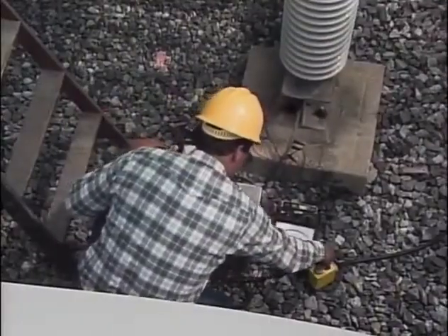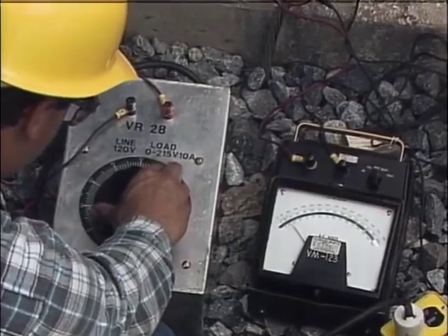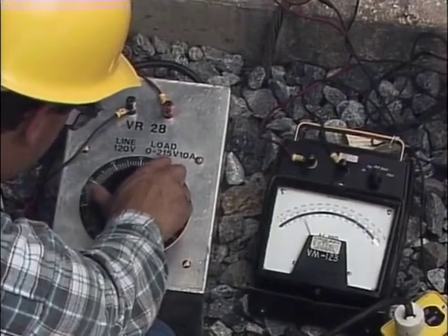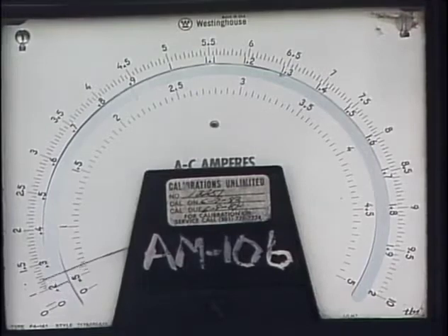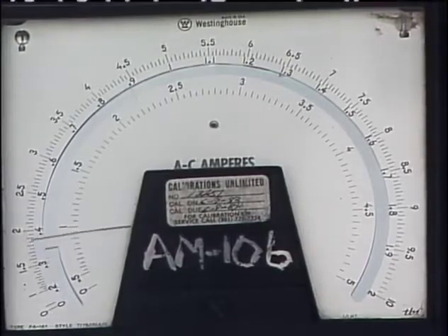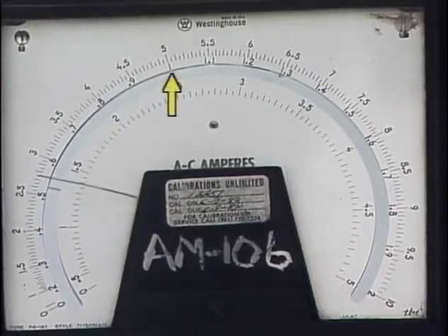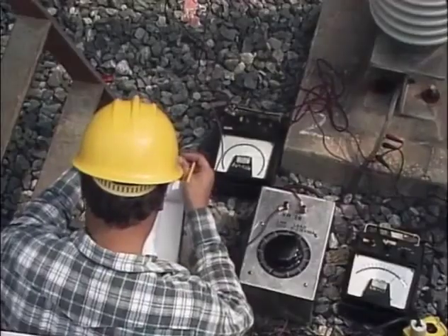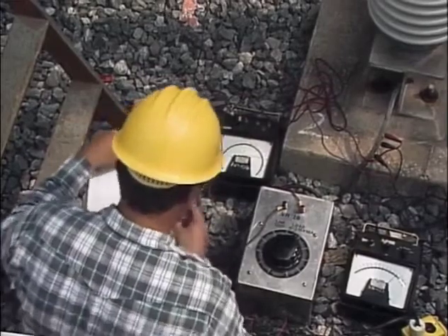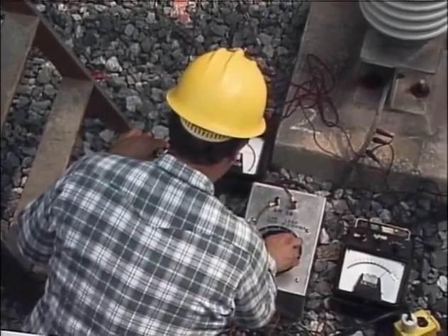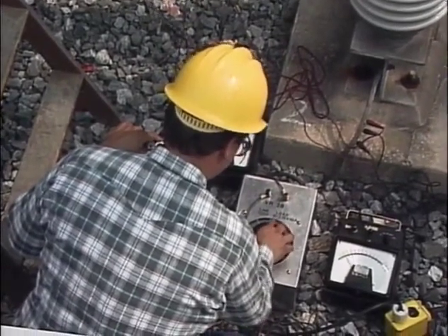The voltage supply is energized. Then it's slowly adjusted until the voltmeter indicates that 120 volts is being applied to the hot terminal of the capacitor. With 120 volts applied to the hot terminal of the capacitor, the ammeter will indicate any current that flows through the capacitor to the neutral terminal. The current will usually read less than 1 amp. Using a conversion chart, the current reading can be converted to capacitance and compared to the manufacturer's acceptable range. If the capacitance is not within the acceptable range, the capacitor should be replaced.